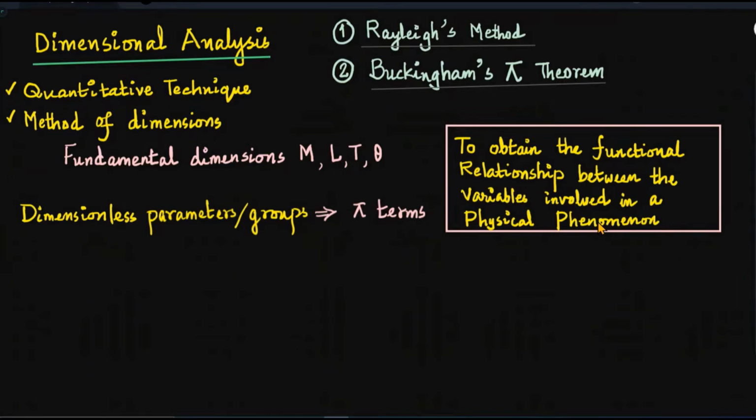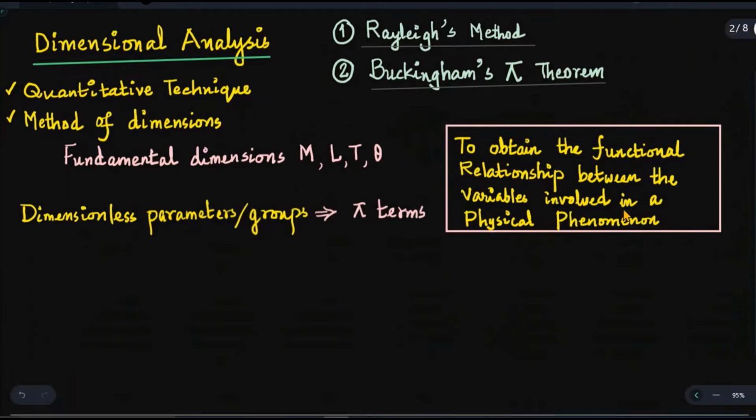If we use these variables mu, V, K, then D, L, all these basic variables involved in this problem, and try to connect them with the pressure drop occurring in the turbulent flow through the pipeline, then we can arrive at a functional relationship using dimensional analysis. So let us make use of the Buckingham Pi Theorem for this purpose.